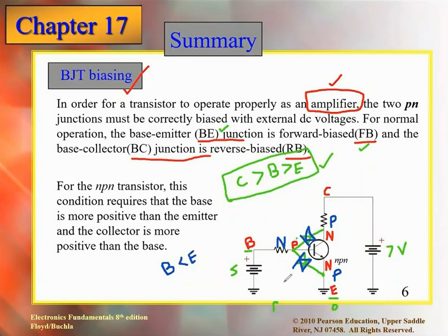Now this is in forward bias. Now I want to make it reverse bias. We already set the voltage at B. Now how much voltage should I apply? Should C be greater than B or C be less than B, so that this junction is in reverse bias? Less, B should be greater than C, or we can say C should be less than B. Check here please. Is that what you are trying to say, all of you?